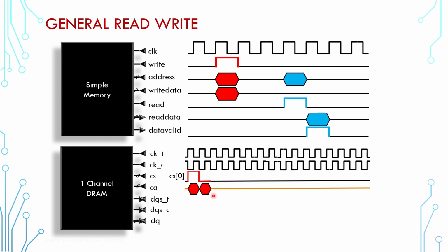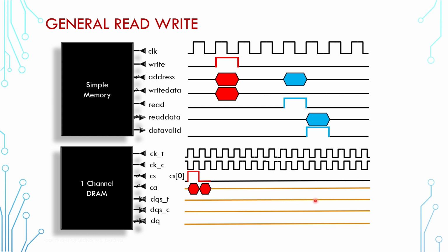Now let's say we are sending a write command. The DQS and the DQ may be in high impedance at first for saving power, so we need to kickstart the DQS. Once the DQS are stable, we can send the data through DQ. For DDR, data are sent in burst mode, meaning that if we send an instruction to write to address 0, we are actually writing to address 0, 1, 2, 3, and so on. Common burst length is 16 and 32, but we are showing a burst length of 8 here for illustration purpose.